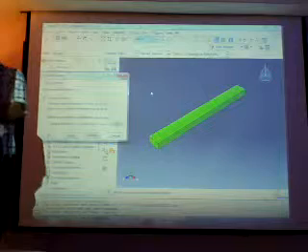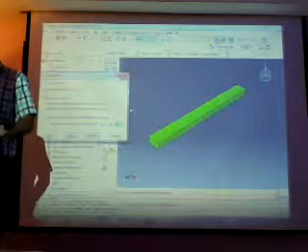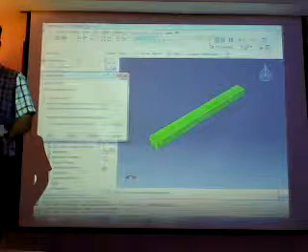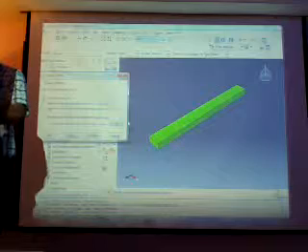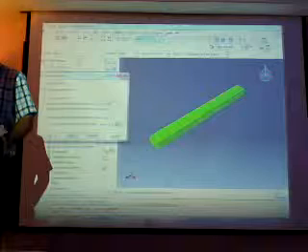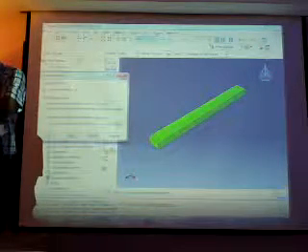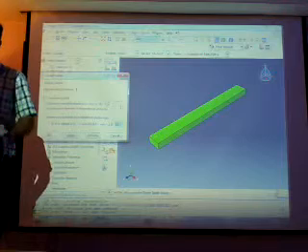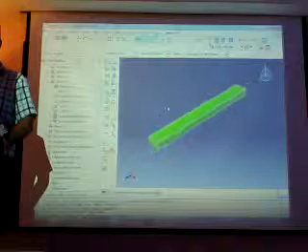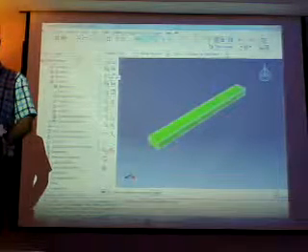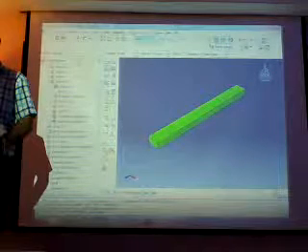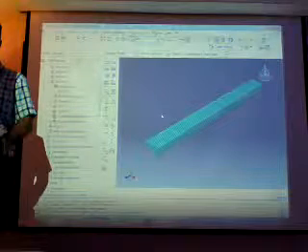For example, here we can take one. And different kind of control you have. For example, if you have a curve, you can decrease this one to, for example, 0.05 to increase your accuracy in simulation. Now we don't need that because we don't have curve, so 0.1 is okay. And our part is seeded. After that, we have a mesh section. I mesh the section. Okay to mesh the part? Yes, and our part is meshed.